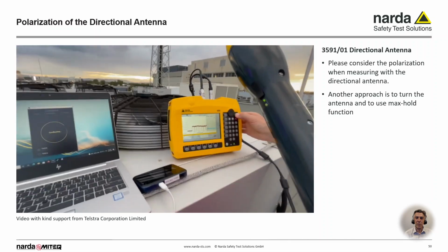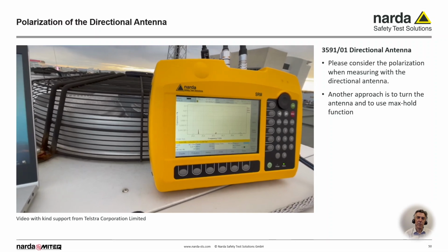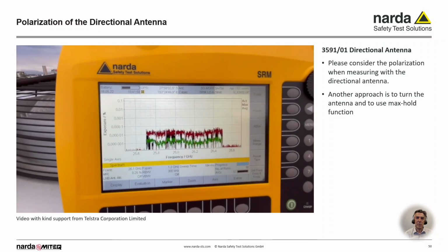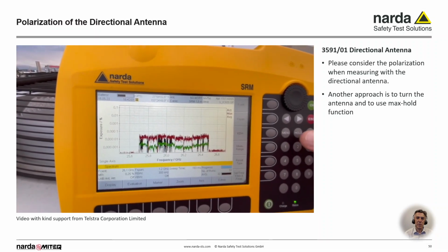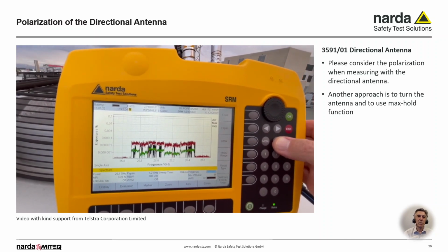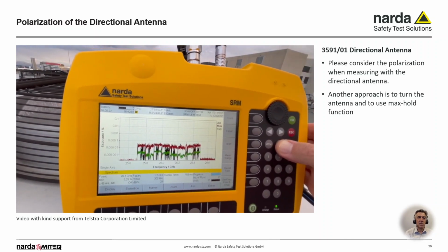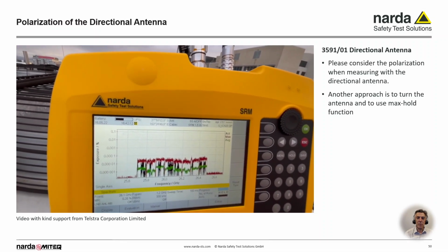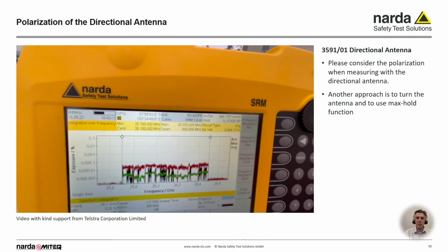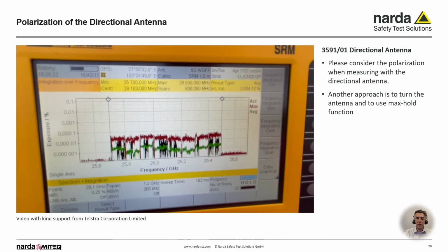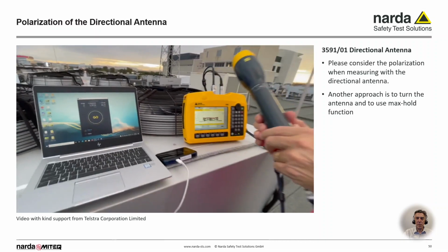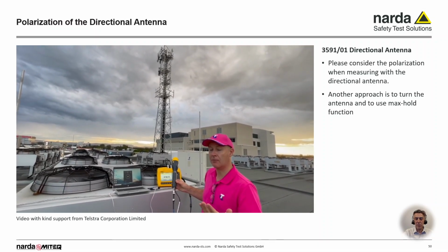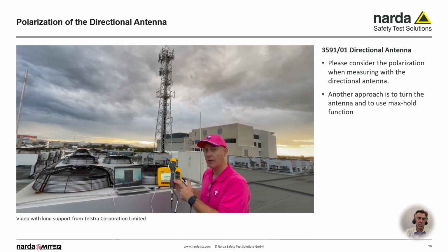I'm running another speed test. I'm going to hit the reset button but change polarities. So now I've got the other polarization, and once it's finished reading its downlink, I'll push the hold button and it's pretty well finished. I'm going to hold that, and now I'm going to do an integration. So evaluation, integration, and we measured 0.00412. So we have to add those two values together to give us the actual power density or the actual field strength relative to the standard at this location.